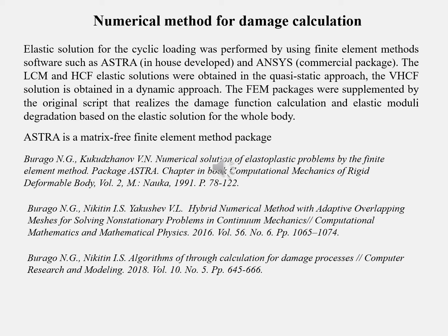Based on this solution, we can calculate the damage function in each node. These calculations we do with a self-developed code that is integrated in ANSYS or Abaqus or another program, and we calculate the damage function in each node of the mesh. With this value of the damage function, we can recalculate the effective elastic modulus and start the new calculation with the new parameters.